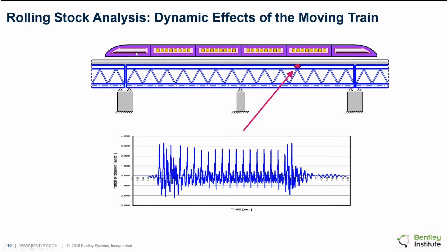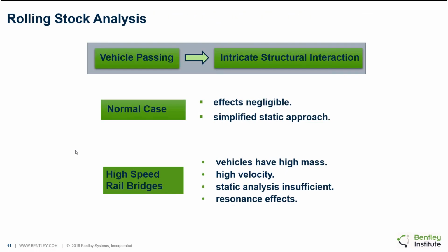And of course, it's a special load as well, right? It's not only the speed, but it could be heavy cars and different configurations, right? So it's not just applying, when we talk about rolling stock, our standard live loads like when we design a regular bridge and we just place, for example, the HL93 truck, right? And we just place the truck in different positions and analyze basically this as a load case scenario, right? A live load case scenario.